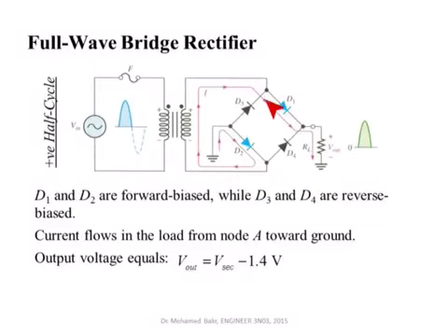In other words, D1 will be on. It will pass a current to this resistor. The current will come back again to here, and then it will pass a current through this resistor and then back to the negative terminal of the winding. Okay, the current will go this way during the positive half of the cycle. So if you have here, say, the voltage here is 15, this diode is on, so the voltage here is 15 minus 0.7, and then the voltage here is 15 minus 0.7 minus the drop across this resistor.